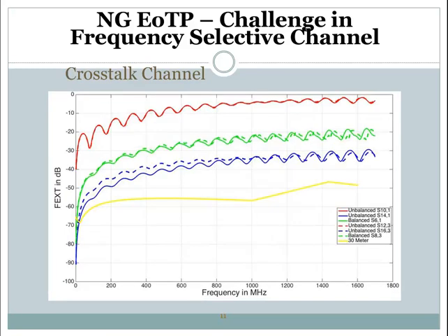This slide is about the crosstalk performance, or more specifically the far end crosstalk, the signal leakage from one transmitting side and received at the other end. Again, the 30 meters long standard cable has the lowest crosstalk due to the longer cable length, and the crosstalk signal is well attenuated.